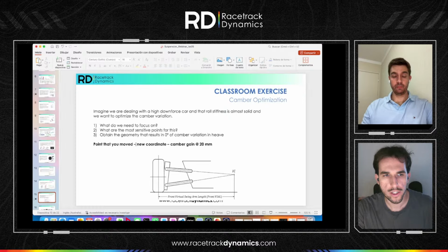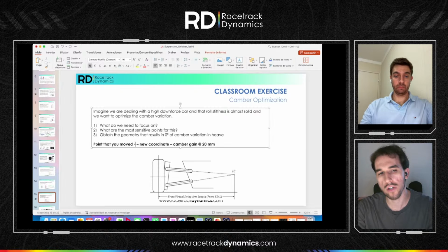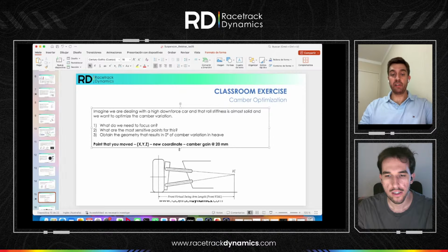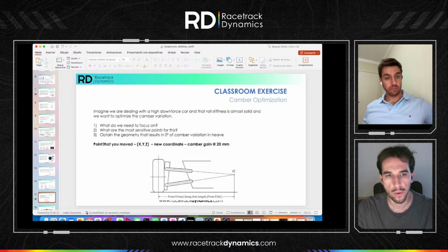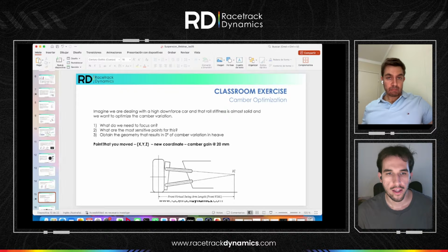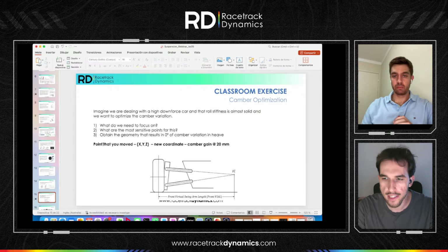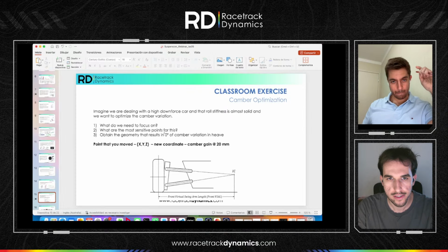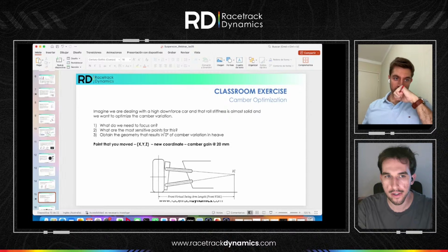Okay, Javi. Question: are they supposed to only move one point, or are they allowed to do whatever they want? Whatever they want. They're free to do whatever they want. Okay. Then, yes. In that case, chat, go on the KineSolver, and based on what the default suspension is, try and play with some points to see if you can achieve this effect. Okay, to see if you can optimize the camber variation.